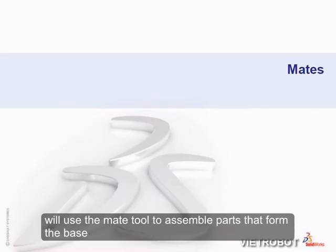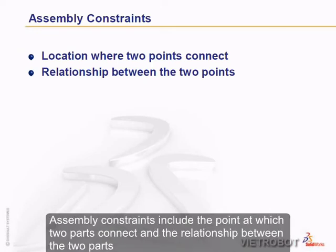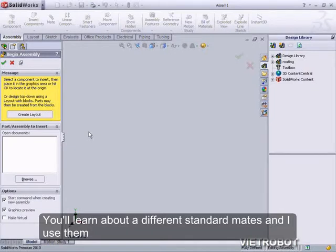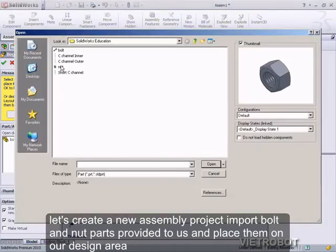We'll use the Mate tool to assemble the parts that form the base. The Mate tool uses assembly constraints to assemble the parts. The assembly constraints include the point at which 2 parts connect and the relationship between the 2 parts. Before we can create our robot base using the Mate tools, we'll learn about the different standard mates and how to use them. Let's create a new assembly project. Import the bolt and nut parts provided to us and place them as shown in our design area.